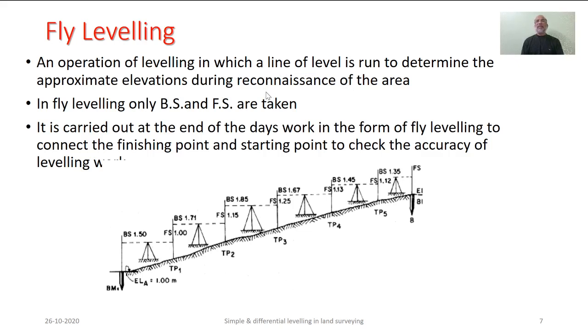As we discussed previously, reconnaissance is the preliminary step as far as land surveying is concerned. So, during the reconnaissance, we are to understand exactly what kind of elevational differences we could be dealing with in the detailed surveys. So for that, we carry out the fly leveling.